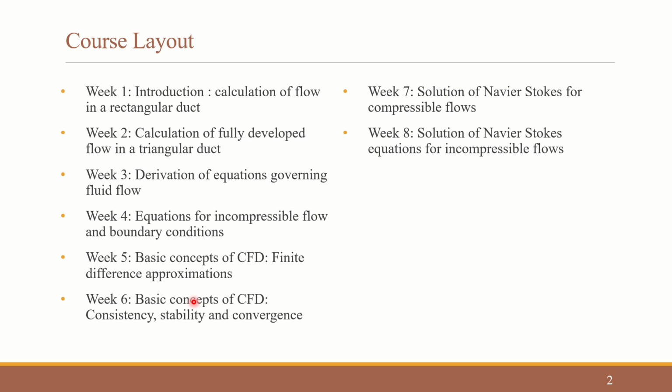So for the compressible flow systems, we had various methodologies like the MacCormack scheme, the Beam-Warming scheme, etc. to get the solution. Whereas when we come to incompressible flow systems, we have these issues which I mentioned. So we used things like the pressure artificial compressibility method, in which we introduce an additional term and get solutions similar to the compressible flow systems.